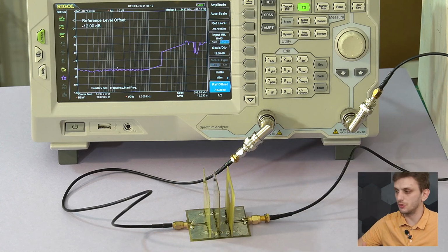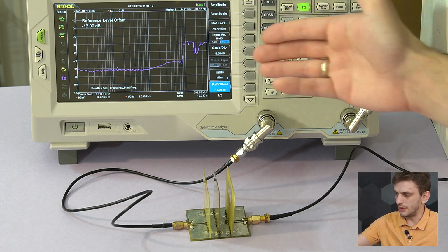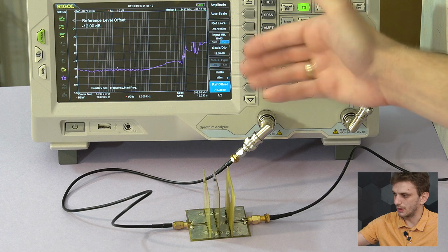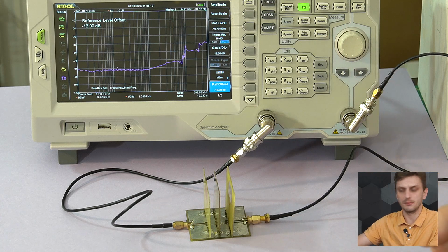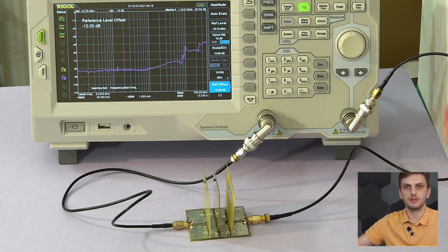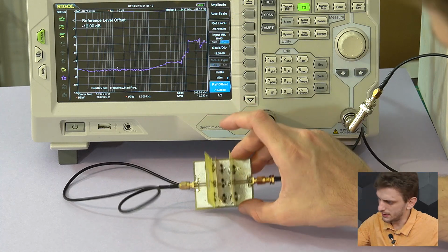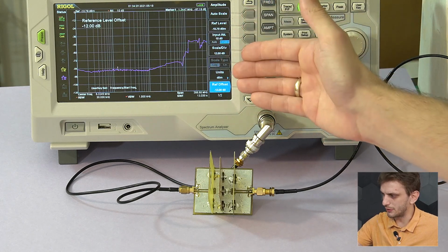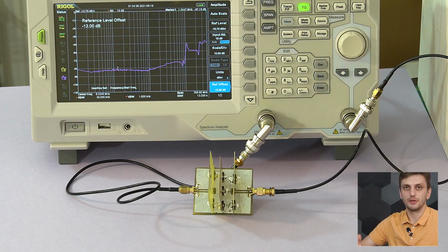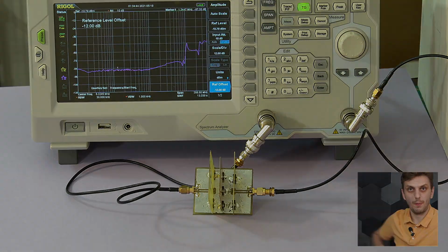with a low impedance connection to ground, we see that now we have a much lower coupling. So we still have some noise passing through. That has to do with the exact physical position in which it is, but we see a much better shielding effectiveness with this very low impedance connection from our upper shielding area to the ground point. So I centered it a bit better, I think, and yeah, we can get even better results by this. So the better you're protecting your noise source, the better you're closing it inside the shield, the less of the fields will pass through your shielding.